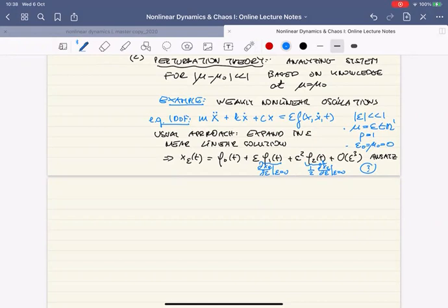Because the ballpark design is already okay, but you had all the damping in the world that you want; your car window is not going to be shaken by some violent force from the engine because you made sure that any interaction between the two is damped. And yet, as your car grows older, at certain frequencies, at certain RPMs, various parts in the car will start vibrating.